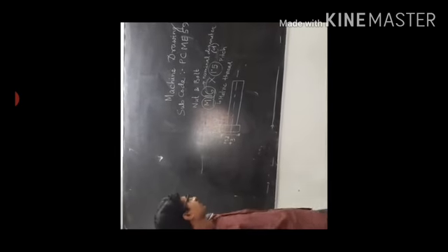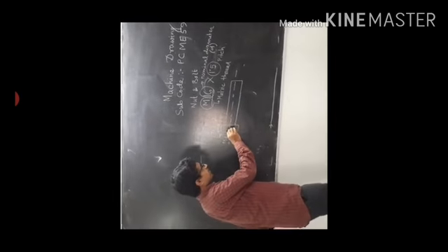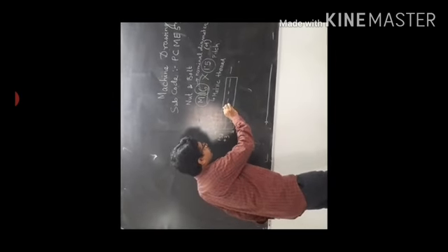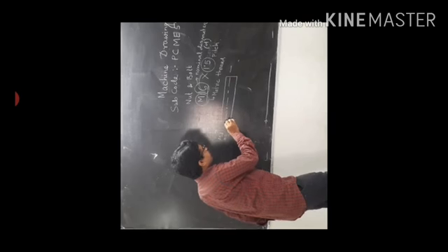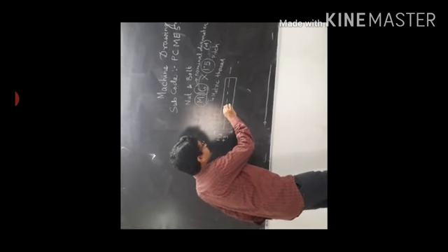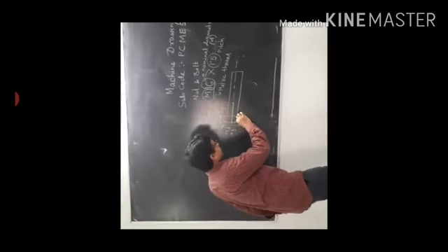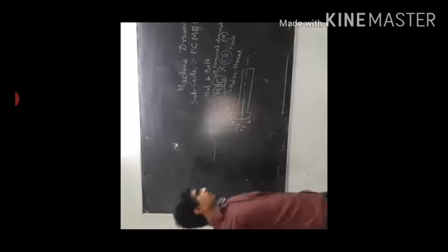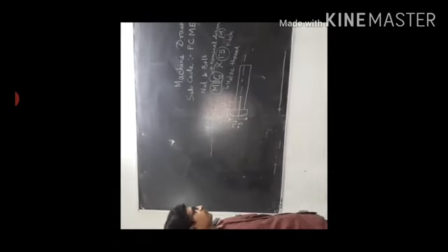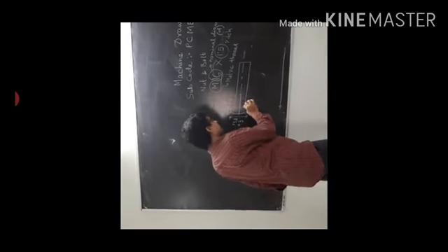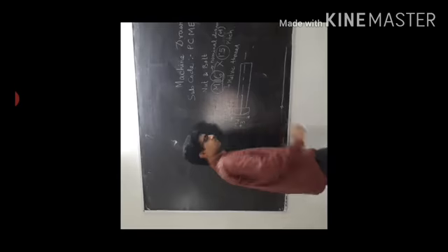And there is a chamfering arc. Suppose this is the midpoint. From here, 1.5t away, there is a center. Put your compass here and draw an arc. And this is the length of the bolt, represented by 40.